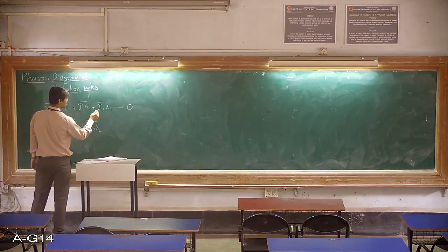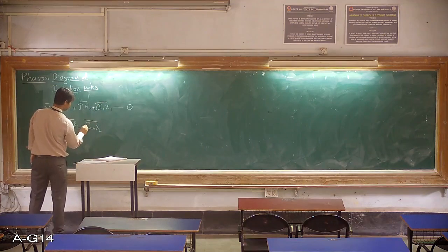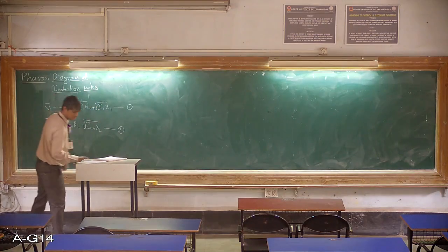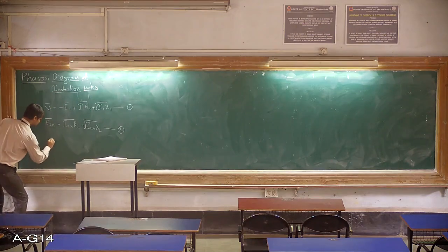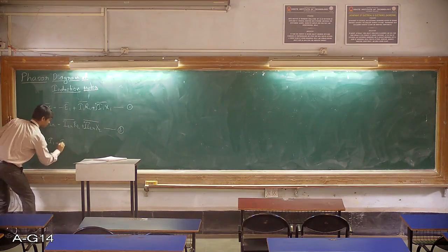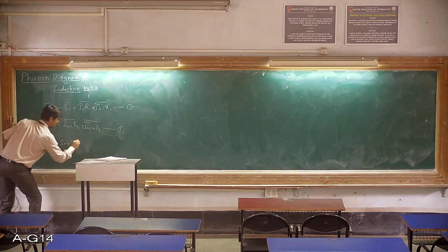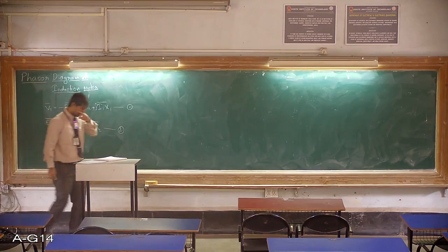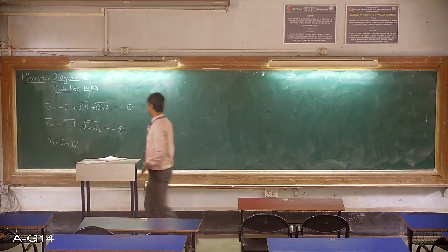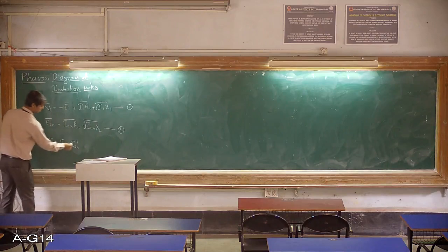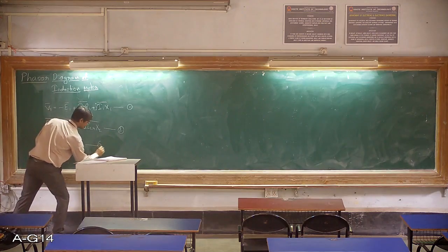And here this is the reactive part. So this is a complex number equation, so the j is written here. Then we have one more equation, that is I1, the total input current to the induction motor, which is equal to I0 plus I2R dash. This I0 is the no load current to the induction motor, and I2R dash is the load current to the induction motor. And this dash is because when we shift the rotor parameters to the stator parameters, we have taken this as dash. This is equation number 3.